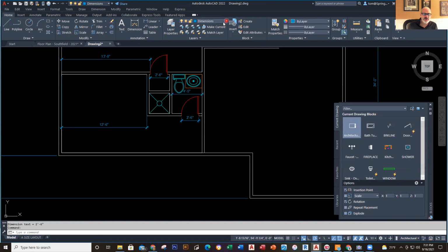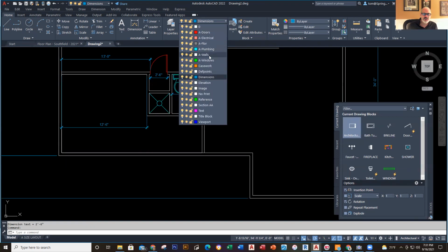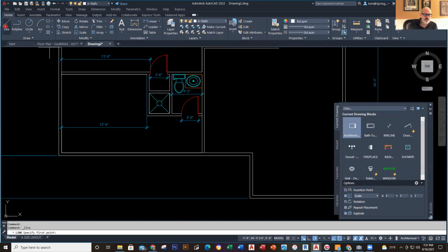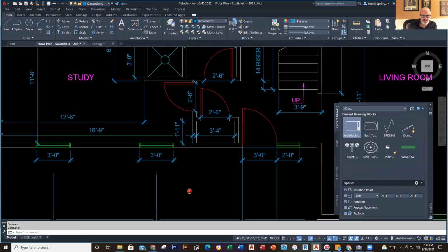So go to my wall command, and we'll do 16'9", and then 2'4". Line. 16'9", and then 2'4", and then we go across that. Except it may be a little different there. Okay. Yeah, I went ahead and did that. Yeah, these are not the same line actually here. So that's what I got to deal with. But that's okay. So we've got that.